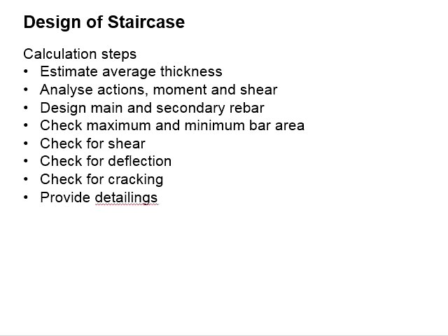Other than that, you will need to check the other serviceability requirements, such as the maximum and minimum bar area, the deflections, as well as the cracking. Then you are to provide the detailing for the staircase.